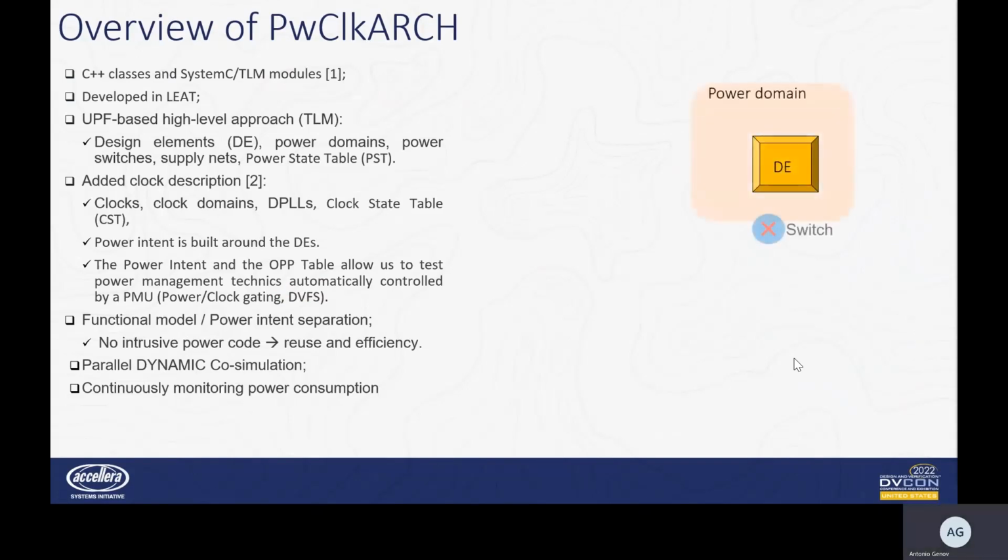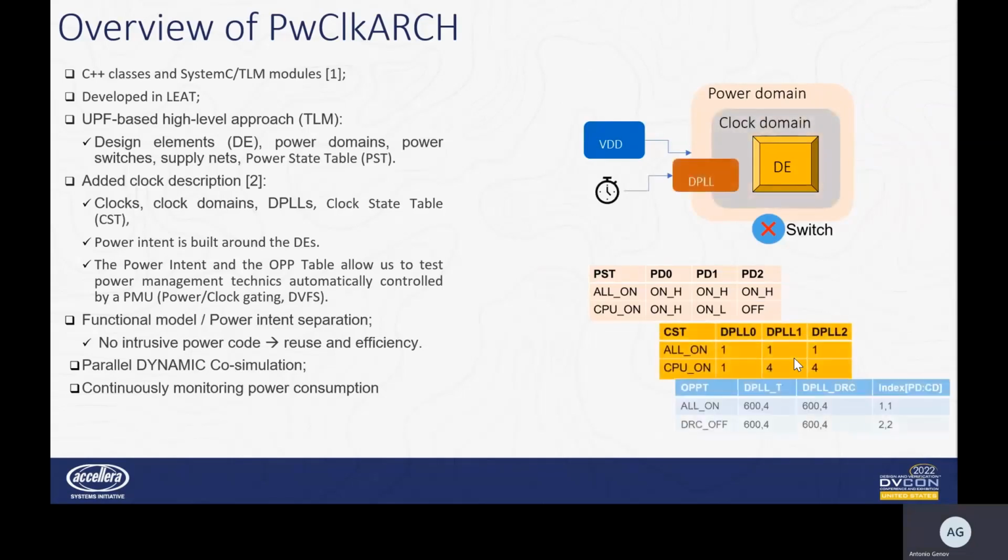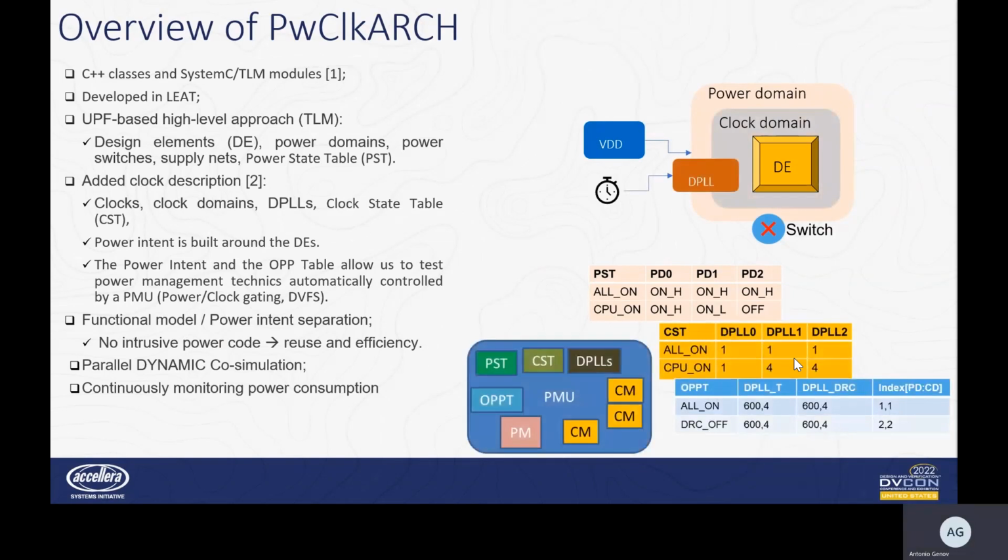It includes components such as design elements containing the power computation for each functional module, power domains, power switches, supply nets, and the power state table identical to the UPF one. Since there is no current standard for the description of clock domains, PowerClockArc introduces a methodology that allows us the insertion of clocks, clock domains, PLLs, and a clock state table identical to the UPF power state table.